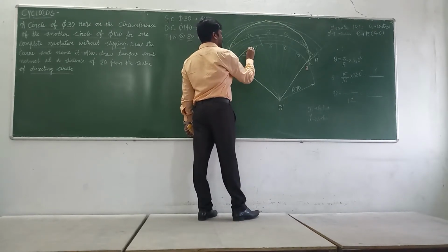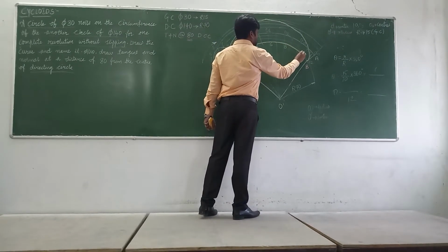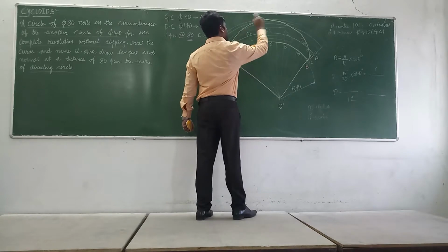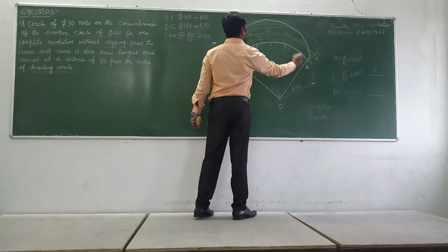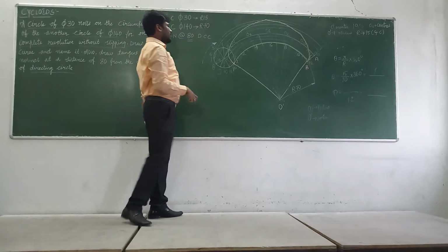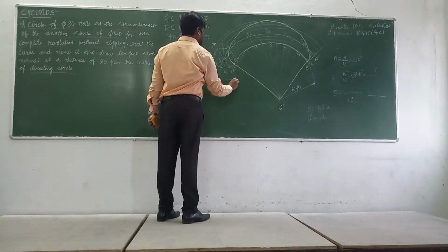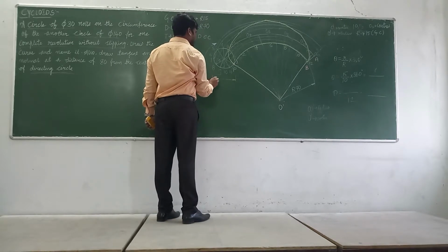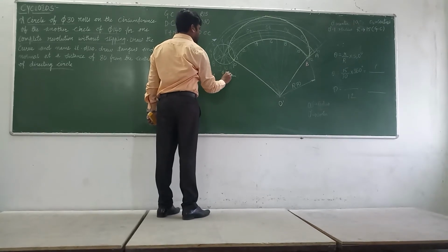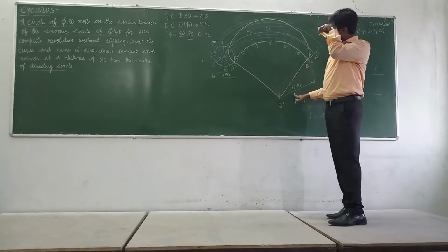So we are going to even draw this directing circle also with an HB pencil. So this is what our curve. It is moving like this. As it is moving, this curve will be of this nature. So whatever I have marked in yellow is my directing circle, and this radius or diameter is to be written compulsorily without forgetting. Why? Because 2 dimensions are given, so 2 dimensions are to be written. This is pi 30 and this is r 70. I hope you got this.